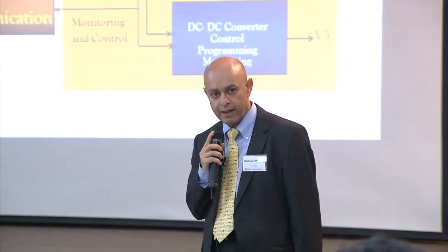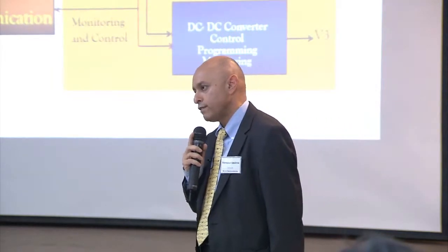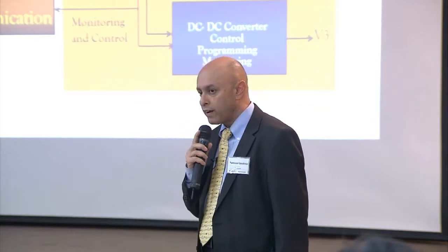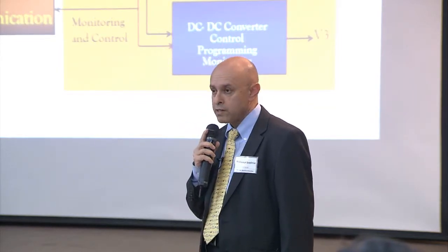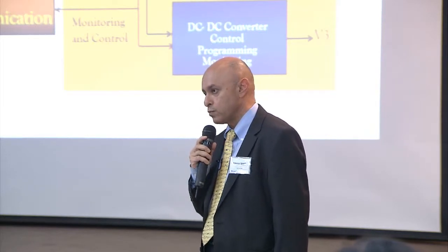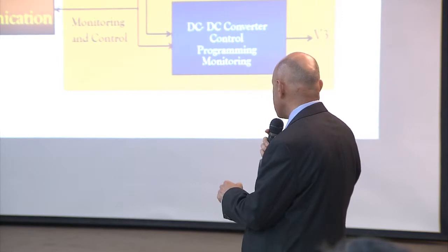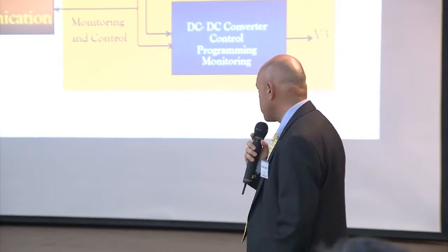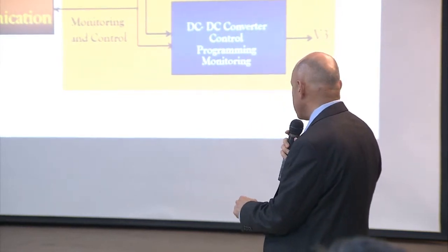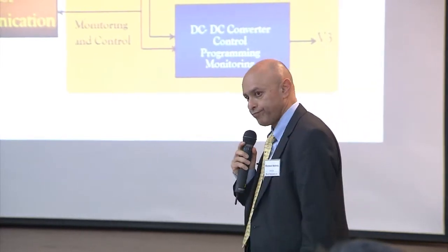In a mobile system, in a cellular phone, there may be 4 or 5 different voltage rails and many different subsystems for the different power management blocks within a mobile phone. In any case, there are multiple DC to DC converters controlling multiple voltage rails. All of these voltage rails are under control and monitoring of a host communication bus.